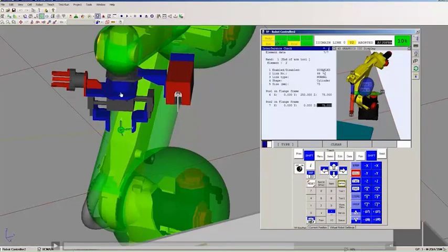So that's going to be X, it's coming directly out of the plate. Y, it's going to the left 250 millimeters, so around where the pointer is. And then Z is 75 millimeters straight down. Now position 2, 0x, 0y, and just Z 75.